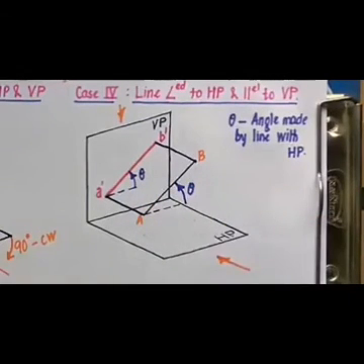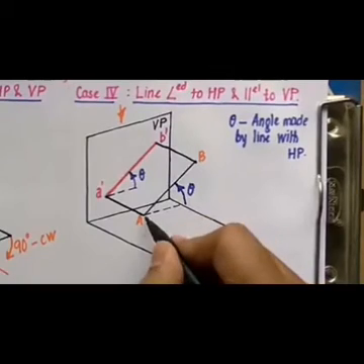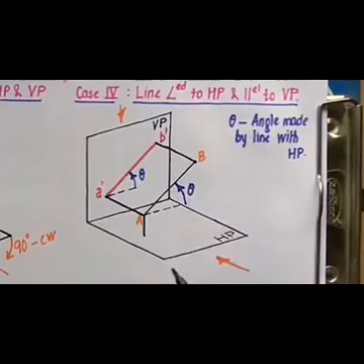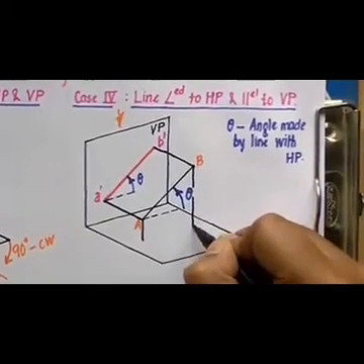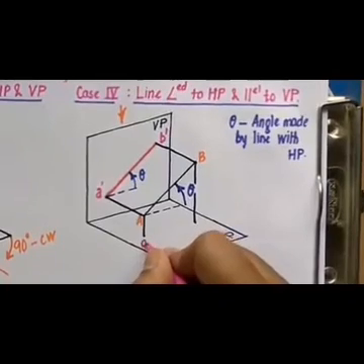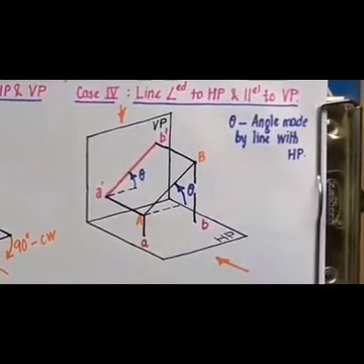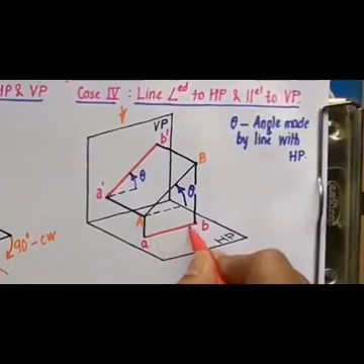Fine. Now similarly, we are going to look at this line from the top, and on looking at it, we'll get the top view. On extending this line in the downward direction, it will intersect this horizontal plane somewhere here. Let us work this out. So this is going to intersect over here. The intersection points are A and B, and when you join A with B, you'll have what you call a top view.